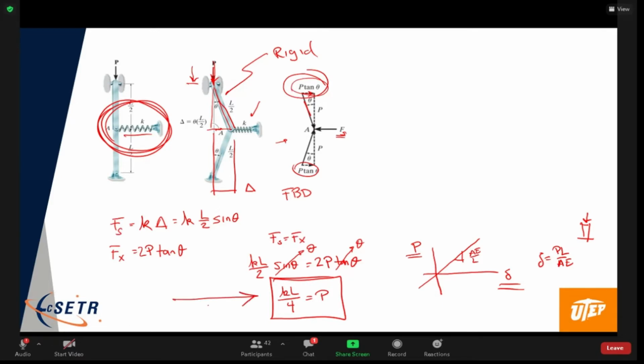that does not happen. The deflection, theta, is what measures the deflection. It's that angle, correct? In the equilibrium equation, that angle doesn't exist at all. It's disappeared completely. And what that means is there is only one load that you can see equilibrium at, where the force is exactly equal to KL on 4. There is no equilibrium unless the force equals the spring stiffness times the length of the element over 4.